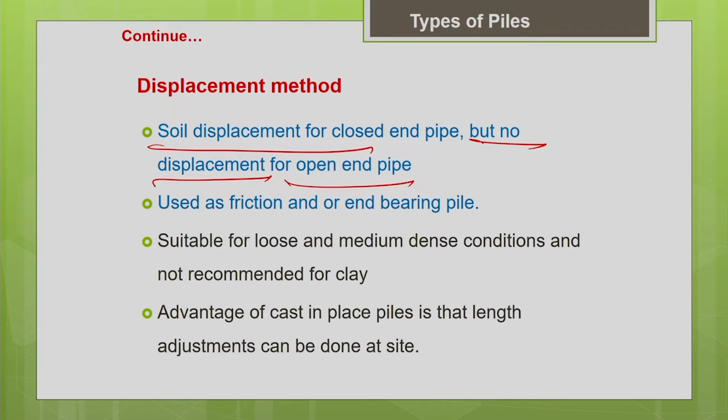So, mostly it can be used as either friction pile or as end bearing pile. You can use it in both the ways. You can use it for loose and medium dense conditions, and not recommended for the clay. As I told you, you never go for displacement method for the clay, because it will result in huge buildup of pore water pressure in clay and heaving.